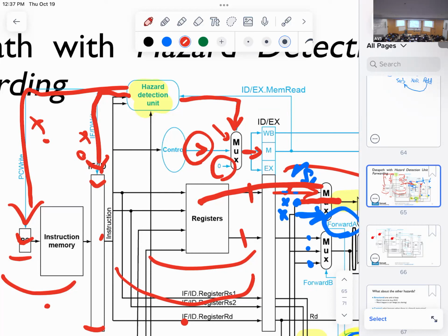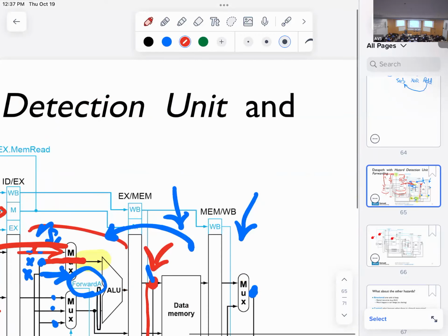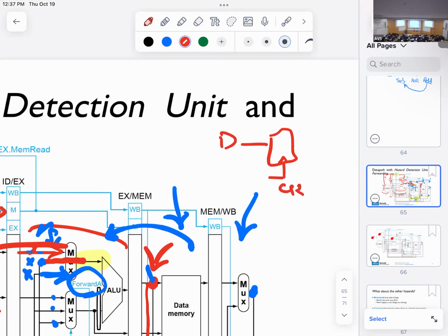Yeah, is it like a D flip-flop, or is that too granular information? Like how do you prevent it from updating? Yeah, so how we prevent it from updating is, if you remember, a very long time ago, I told you that a register has a clock and has data, but some of these registers also have what we call a write enable, okay? So what this does is make this write enable equal to 0. In that case, even if the clock comes and the data changes, this output won't change, right? So this is what we did. It's a flip-flop with a write enable.